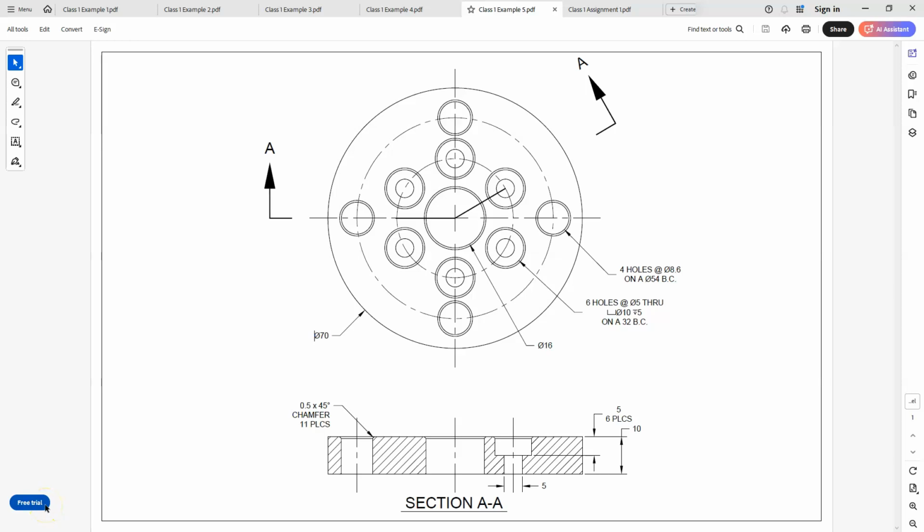Okay, so welcome back to the channel, and in this video we will be creating this part using AutoCAD 3D. Now, we can find another way of creating some of these counterbore circles, and just to give you a preview of that, we will use the revolve command if you wanted to do them all in one step. But since we're using extrusion, we're going to be creating these counterbores in 2 steps. So let's go ahead and jump over to AutoCAD and get started.